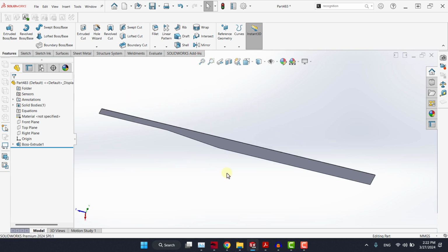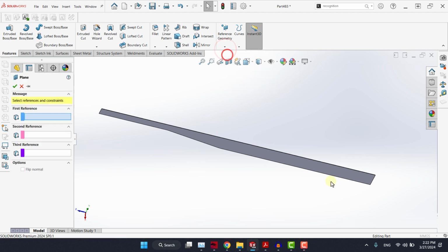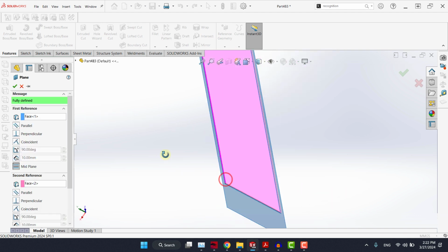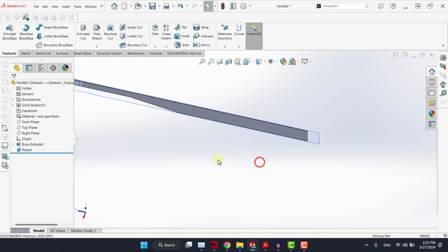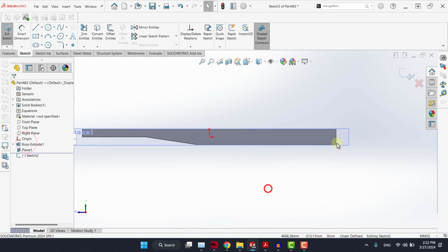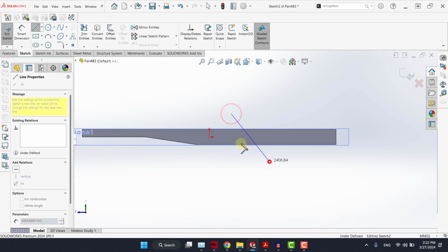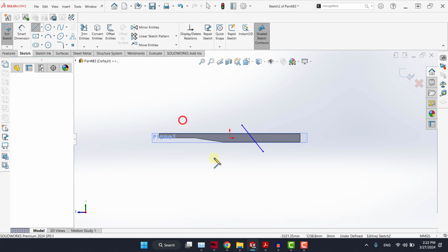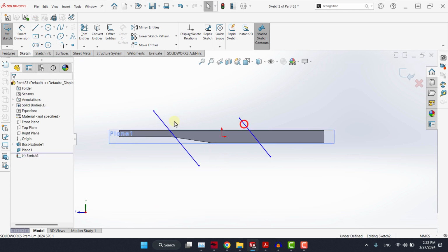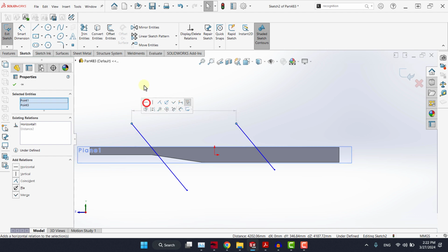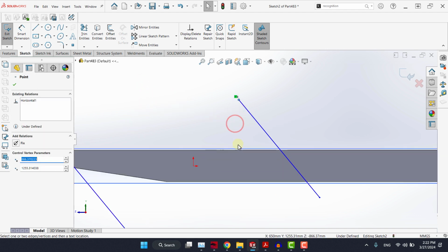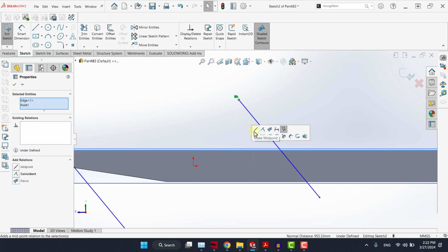Now, to do so, I can start here or on the mid or on the right plane, but I will create a plane between these two faces here, because this will be handy later. We will talk about it in some detail. So I'll start a sketch here, and simply I'll draw these lines. First, I need to make sure they are parallel, and I need to make sure that these two points are horizontal. And I want to make sure that they lie on this edge here.